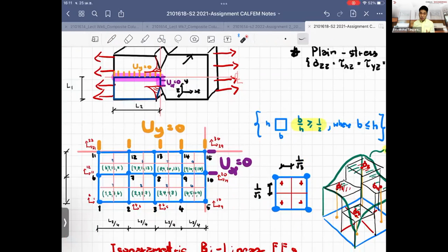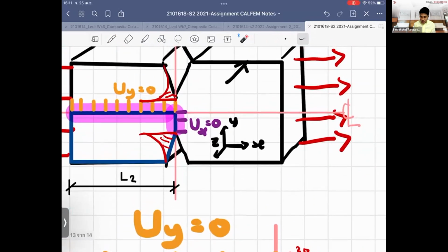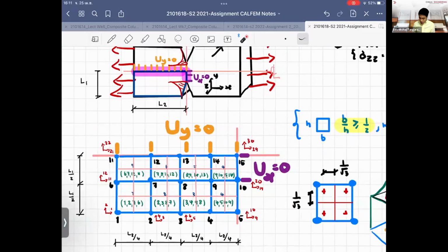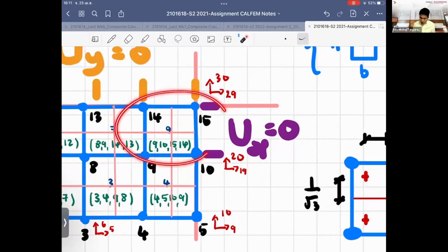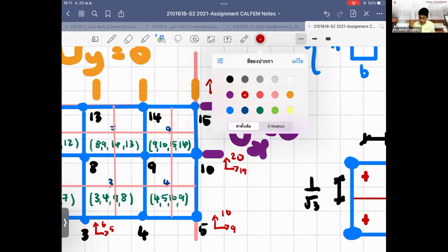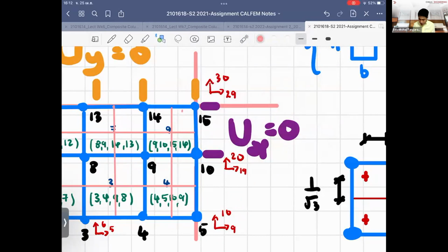Sometimes I will show you the nice element later, right? But in most cases, when we find the problem is this notch, the crack tip is a problem. So you need more elements around the crack tip to approximate the sudden change or the high variation of the stresses, so that we can capture the high order variation of the stress. To satisfy this, I need to discretize this area more. So what we do, definitely, I decide to cut more, divide more elements in these areas.